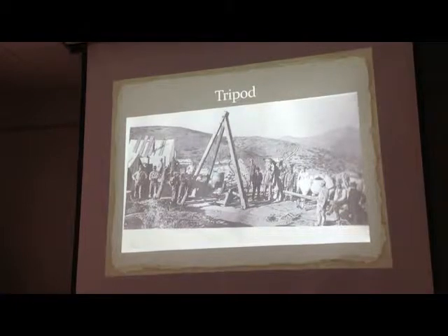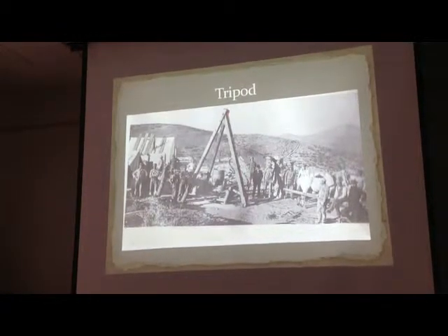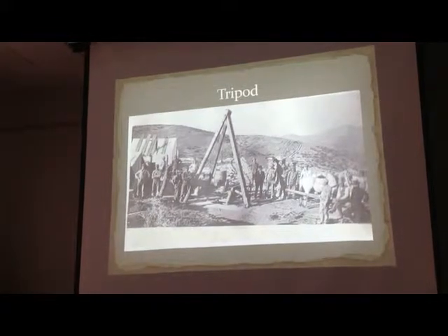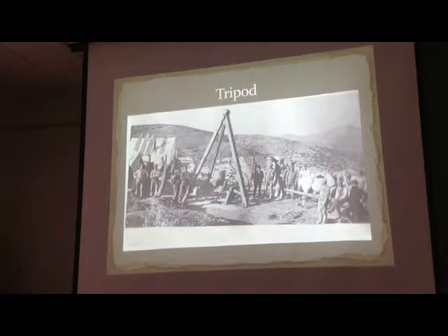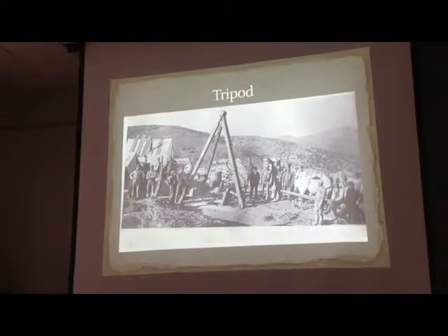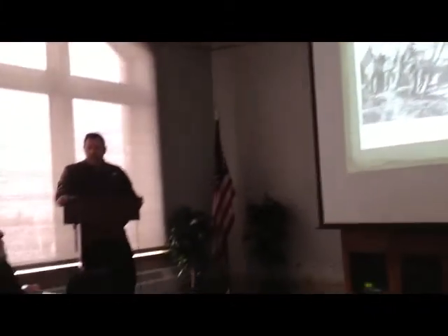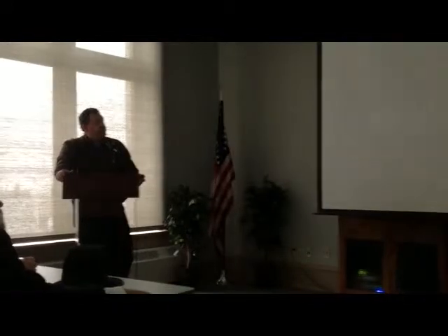You'd have a horse whim, or a whip. You could use a whip also. Rope would go up, and the sheave wheel would be at the top, and then just for shallow bucket hoisting. Usually these would be erected once your shaft reached 60 feet or more in length. But 60 feet or under, you can usually use a windlass with better efficiency than a horse. This one is out of Arizona.